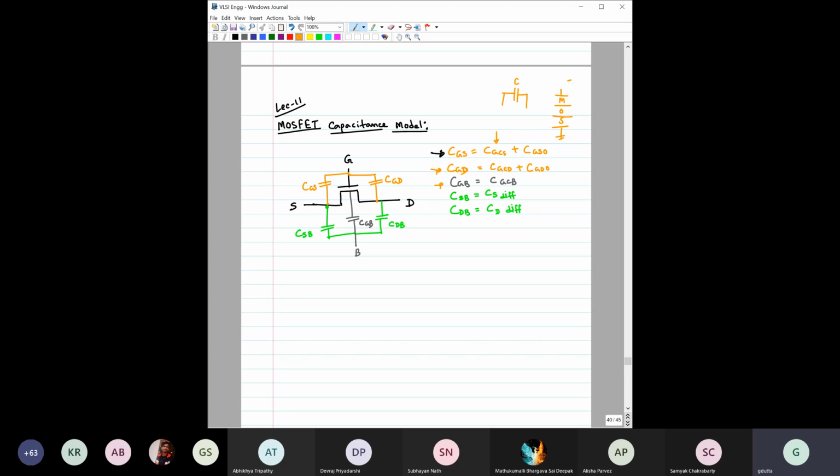So you have to apply some DC bias, operate at some DC bias, and then measure the capacitance. But it does not mean that when this voltage is 0, the MOS capacitance is equal to 0. So we will understand it, and spend some time on capacitor measurement.